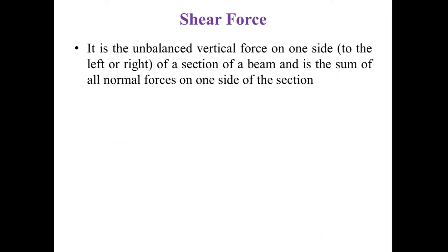Then we come to the concept of shear force. What is shear force? It is nothing but an unbalanced vertical force on one side, to the left or right of the section of the beam, and is the sum of all normal forces on one side of the section. So basically it is the unbalanced vertical force on one side of the beam.